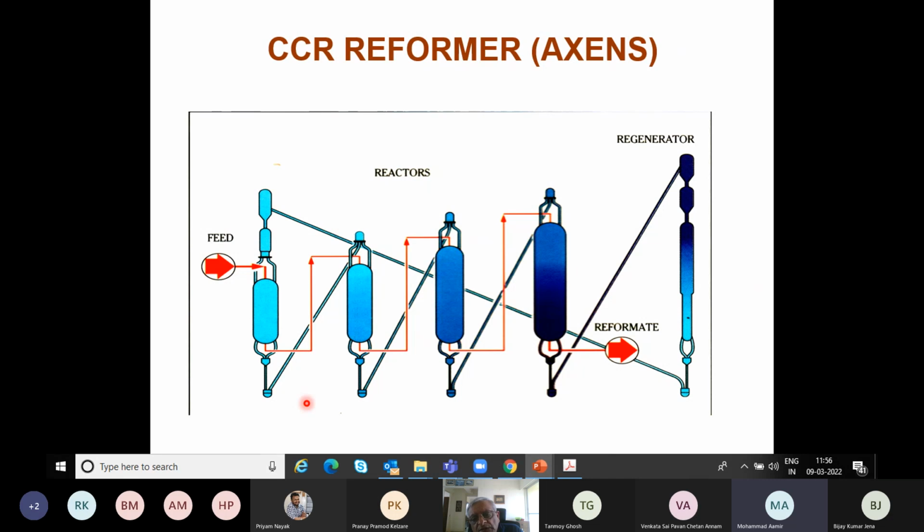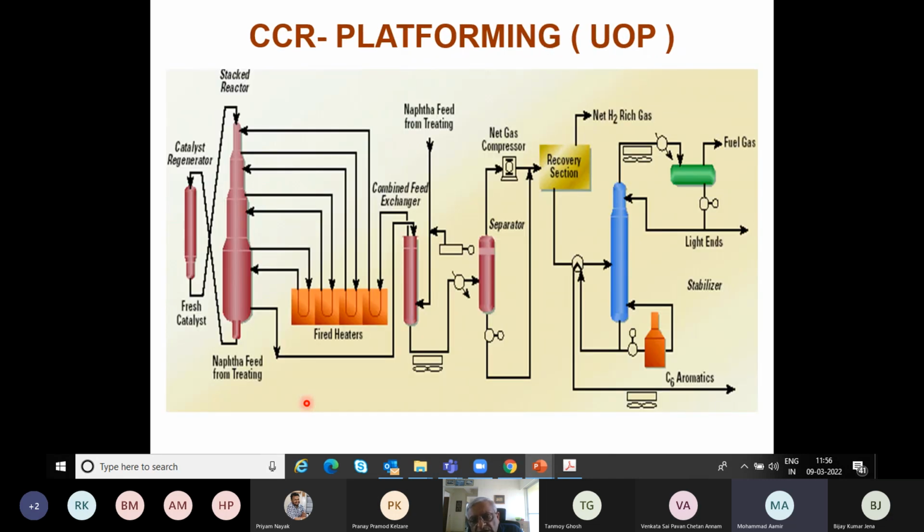So you can see now why these two companies have a different path. It's very interesting the way industry does research. UOP was the first to invent reforming, right? So there was a large body of knowledge, in terms of science, chemistry, technology and engineering at UOP. And they used that to advantage to come up for the first time with a disruptive technology like CCR. They came up with a stack configuration, because it's easy to flow something with gravity from top to bottom. So here the entire catalyst flows because of gravity.